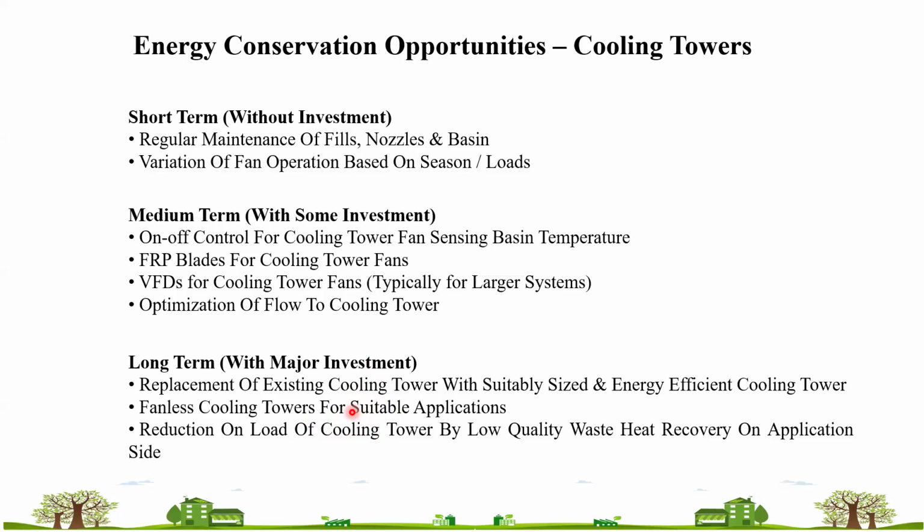Yeah, because we have some cooling towers of around 150 TR, and the height and dimension of this cooling tower is very big. And if I wanted to go for 400, 500 TR, the size will again be very big. So it will not be practically possible for us. You can install a 150 TR fanless cooling tower, but the height of that cooling tower is on the higher side because you need to provide more area for the water to come in contact with the air.